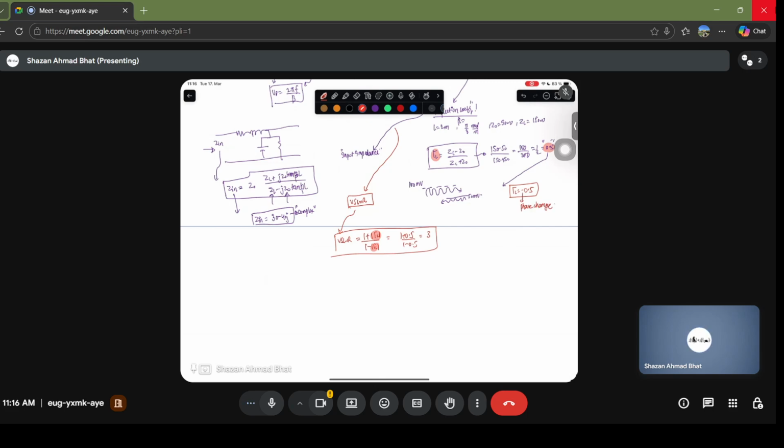But what happens if you have an electromagnetic wave coming in like this, and it goes back exactly like this? Then there is no phase change, and the reflection coefficient will be positive. But if your electromagnetic wave comes in like this and it goes back in a phase-changed fashion, you can see that the phases are flipped, and then your reflection coefficient is going to be negative.